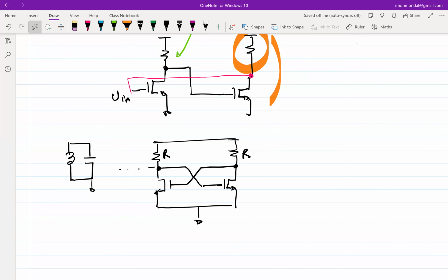We can use a tunnel diode, but the issue is it's not easily integrable in a CMOS substrate. Because it is not easily integrable, we tend not to use it. If tomorrow some new device comes which is easily integrable in a CMOS substrate, we are going to forget CMOS and use that. So it's all about how economic it is to integrate a new device. Among all the technology available till now, CMOS is the least expensive, most economical way of designing analog circuits or any integrated circuit.